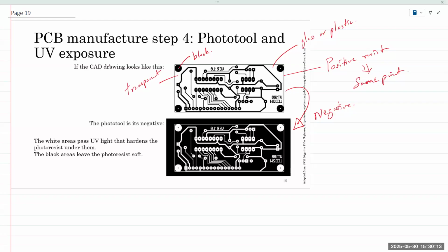The areas where the light goes through and hits the photoresist are going to be affected. If it's a positive photoresist, the light affected areas are going to be etched away or removed. So what is left behind on your photoresist are the areas where the light is blocked, which is your pattern. And so you get an exact replica of this plate on top of your PCB.